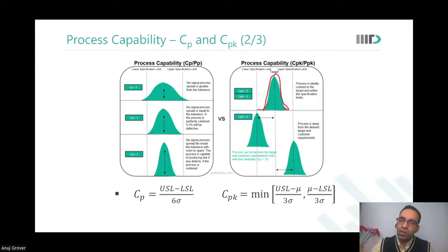So I have this kind of a Gaussian which is plus minus 6 sigma on each side. But in reality, the process may shift a little to the left, a little to the right. The typical process corner is centered right on the target, but slow and fast process corners are also there. So the slow and fast process corners would be here, or could be here, as they have shown. Suppose my slow corner is here. What does this mean?